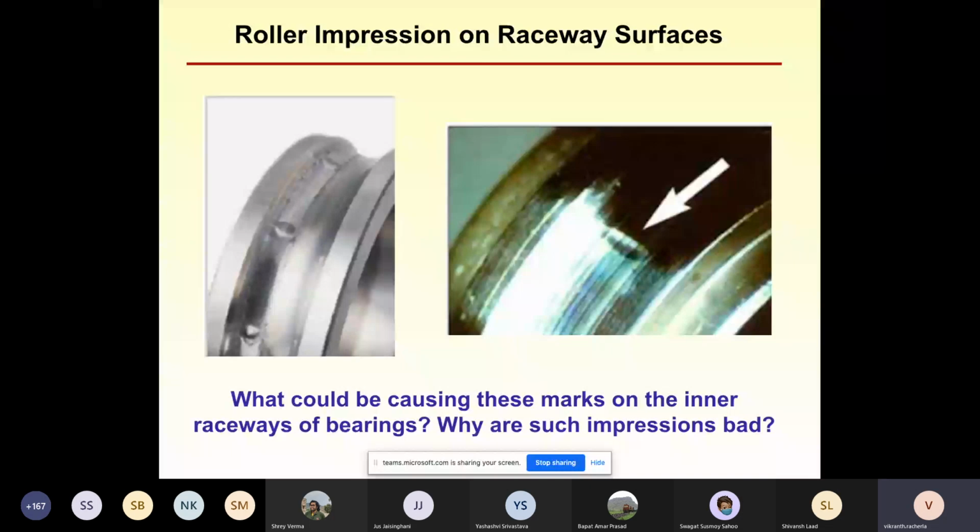There are a bunch of different bearings which you can use. You have journal bearings, where you can either use some hydrodynamic effects, or you can use plain bushings, air bearings. There are a lot of other options, but by far roller bearings are the preferred way of supporting rotating shafts within a system.